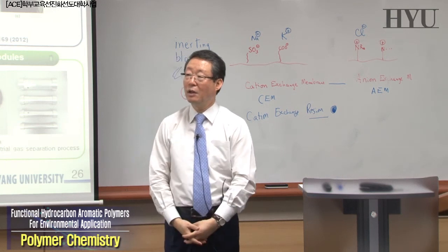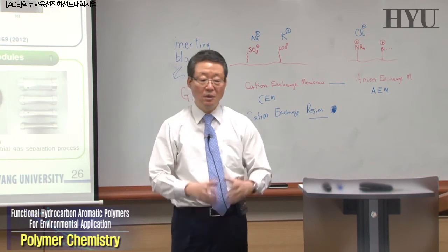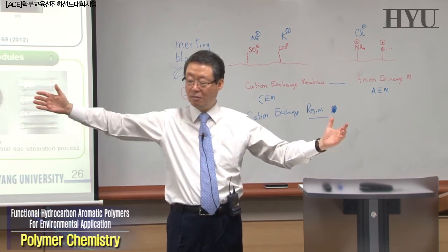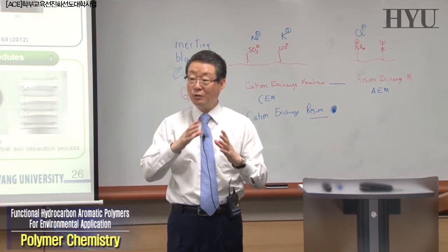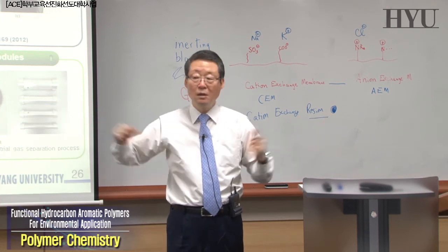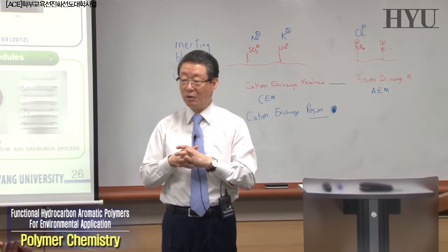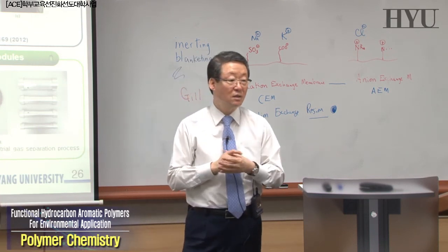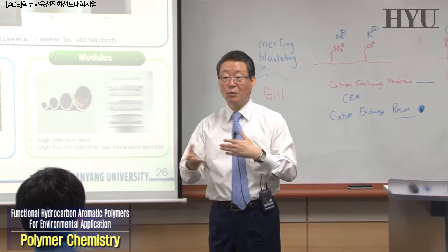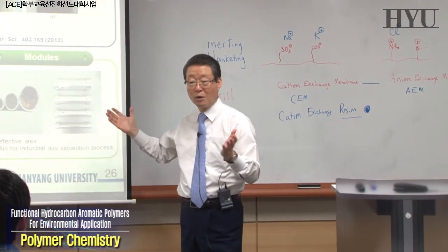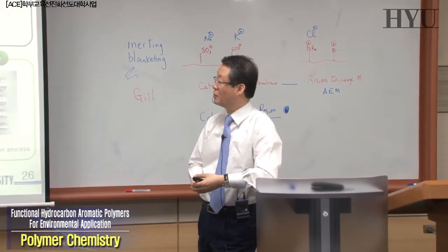Right now, the Boeing 747 needs to have big modules. I think they have to have at least 10 modules with a big size to supply the blanketing nitrogen gas to a fuel tank right now. Okay? The weight of those big modules is pretty large, pretty heavy, so they want to replace them with smaller modules, if there is very high separation efficiency of those membranes.